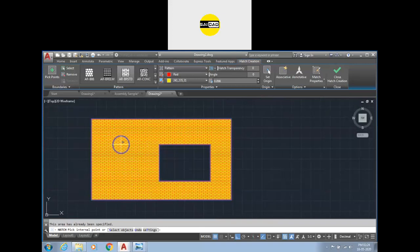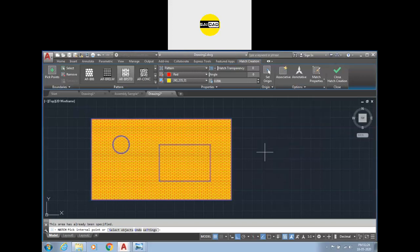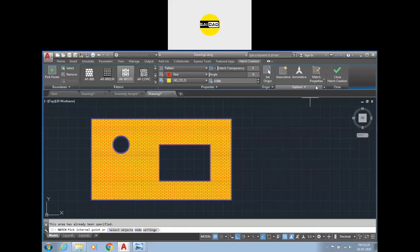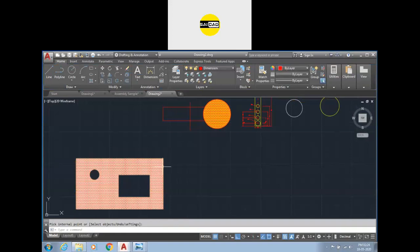If you are unable to select that object or that area, you can just go to the options. There is an option called island detection, and here you can click on ignore island detection. So hatch will be added inside of this geometry. It will not consider these geometries. If you select the island detection to outer island only, it can be created like that. You just close, the hatch can be created like that. Is it clear? Hatch option.